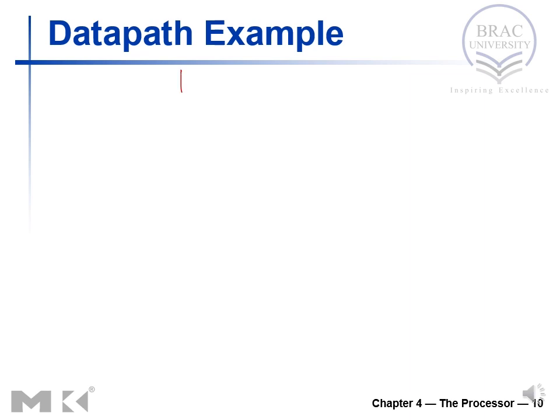So the instruction is BNE, let's say 10, 11, and then else. So we all know this else is 16 bit, so we need to make it 32 bit. And this branch not equal to, that means ALU would compare the value of register 10 and register 11, and if they are not equal, then the branch pointer would go to the branch target address. To design the data path, we all know the first component that we would need.